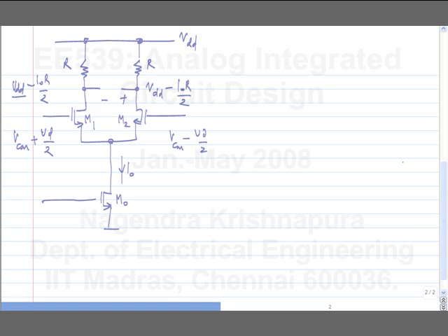okay, and on top of it you will have the differential output. Okay. So in this particular case, the output common mode voltage is fixed to some value, that is VDD minus I naught R by 2. Can we use this as an op-amp? We have discussed this before. If you load it with a resistance, you need a very large DC drop across the resistances to have a large gain. Okay. So while it's theoretically possible, it's not practical to use this as an op-amp.